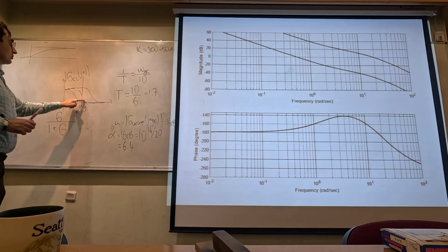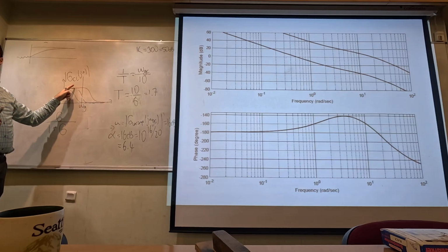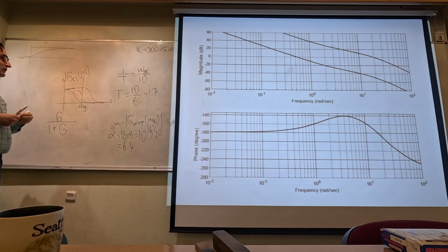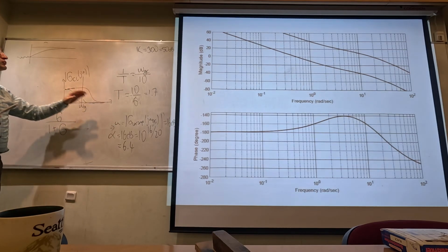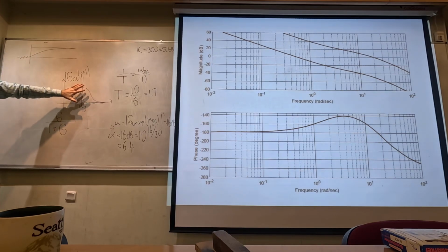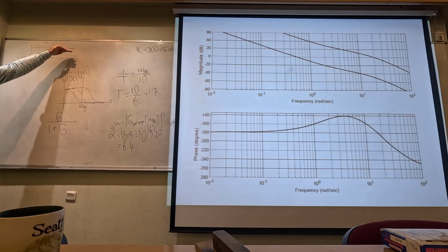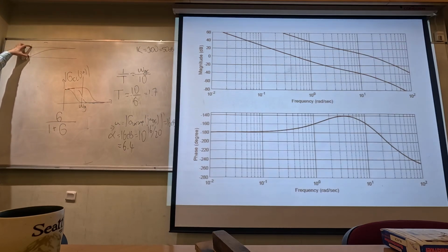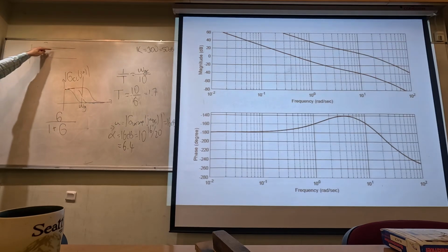This is my response for the middle low pass filter. Here we see that this sharp change in the input is a high frequency component. Okay? If we filter it with a low pass filter, it is smoothed out here. Okay? In the response, you won't see that sharp change, so your response is going to be looking like this.